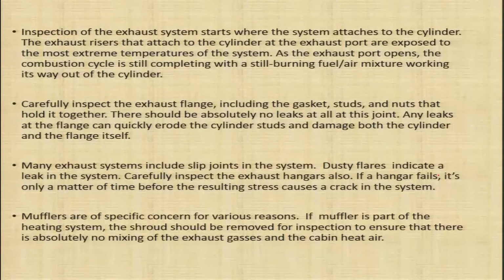The joints, these slip joints, they are designed to have flexibility. We need to inspect these joints very carefully. Dusty flares indicate a leak in the system. Along the joints, adjacent areas of the joint, if we observe some dusty flares, that indicates a leak in the system. Carefully inspect the exhaust hangers also.